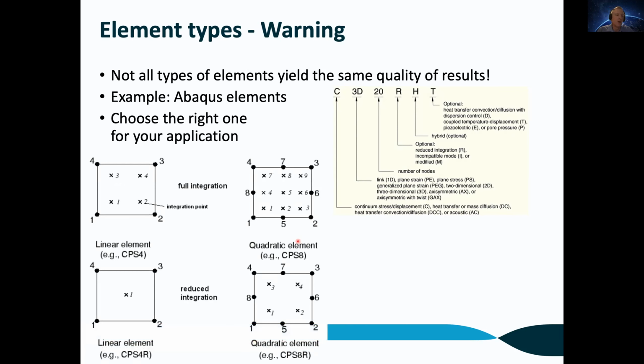I'm not going to pretend I'm going to tell you the whole recipe, but just to illustrate, here's what it looks like. On this drawing, you can see 4 different cases. The 2 on the left-hand side are what we call linear elements. Why are they linear? Because the mesh nodes that we have are connected by linear segments between the nodes. So if I pick my 4 corner nodes, then I've got those 4 sides that are linear. You can see the little crosses that are my integration points. The 2 cases on the right-hand side are what we call quadratic elements. There are added mesh points at the middle of each of the edges, and these extra degrees of freedom allow the geometry to be more flexible and to have a quadratic, second-order interpolation between all the edges.